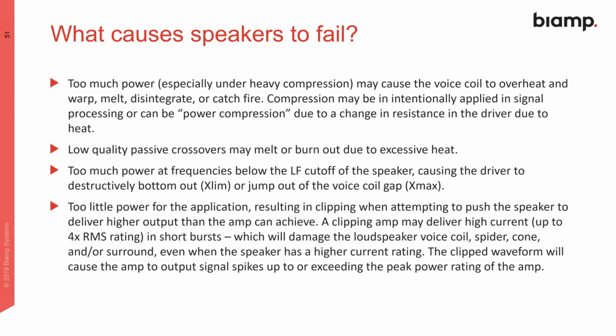So what causes speakers to fail? Typically, this is going to be a combination of things. You're either dumping way too much power into them, and so the speaker bottoms out and just gets crushed in the voice coil. You might have a magnet that shorts across the voice coil. Often that'll happen if there's clipping.